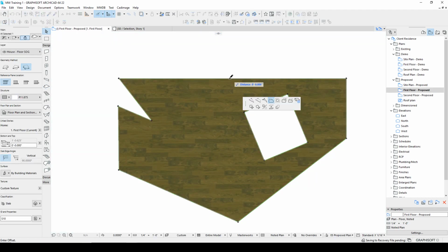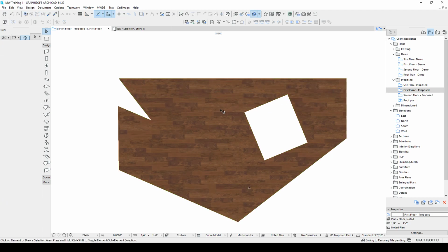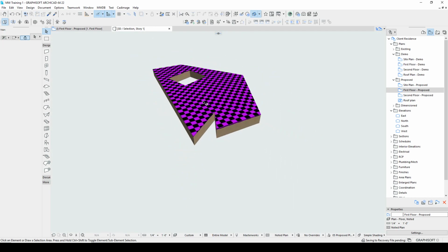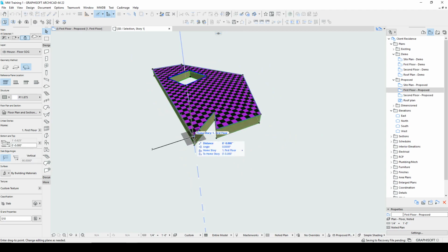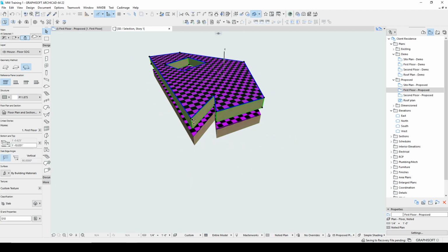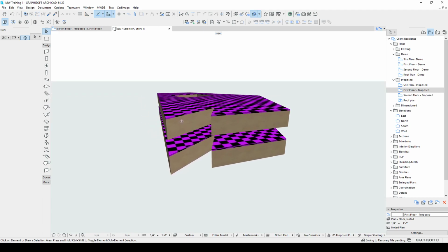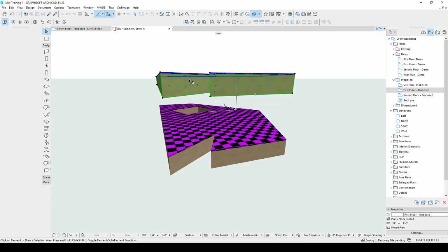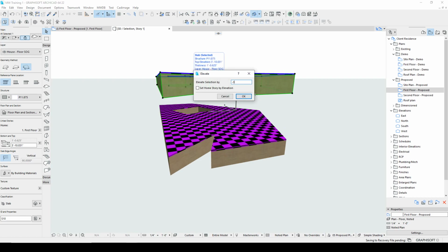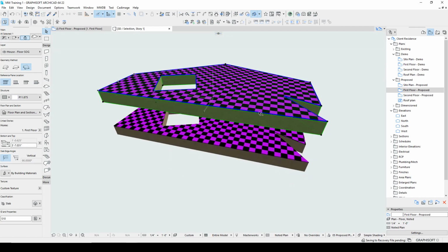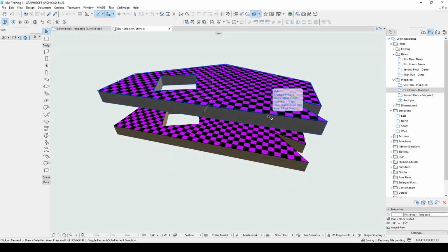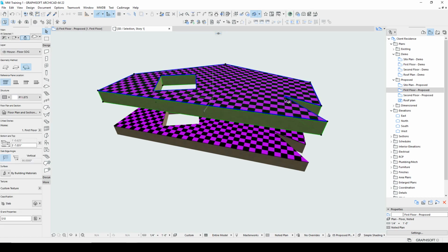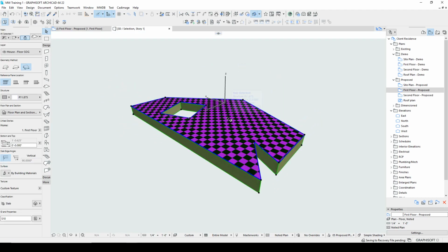Going back into 2D, I can use all my tools. I can change the edge settings. And then a new tool that becomes available. Let me copy this, F9. Copy it up. So I have 2. I just wanted to have something to see from reference. F12 is elevate, and I can just hit a value, and that moves it up exactly 2 feet. F12 minus 3 inches. And this is something I use all the time. That elevate command works for all 3-dimensional objects. So take advantage of that. That's a great little feature.